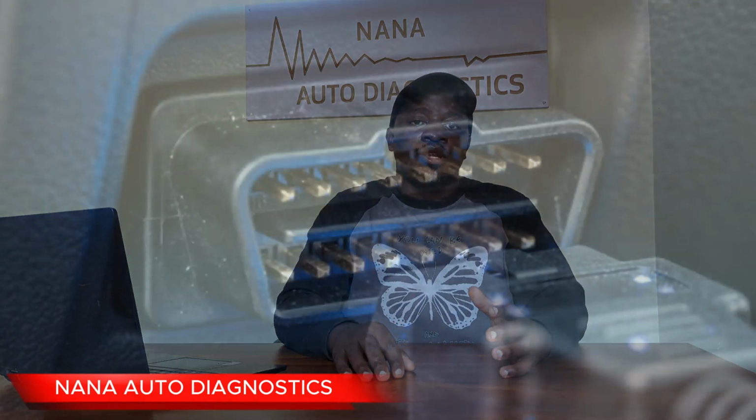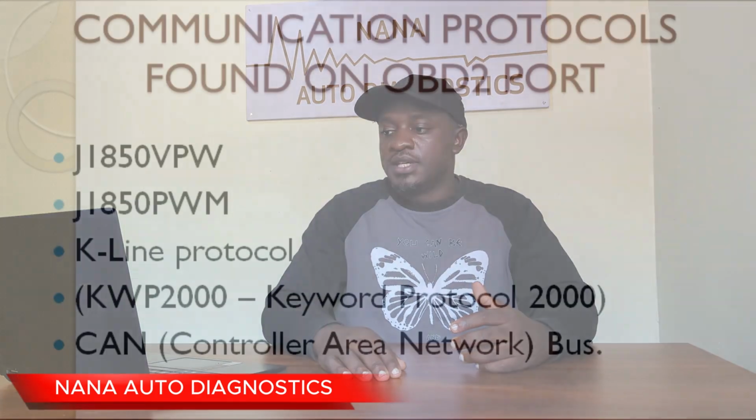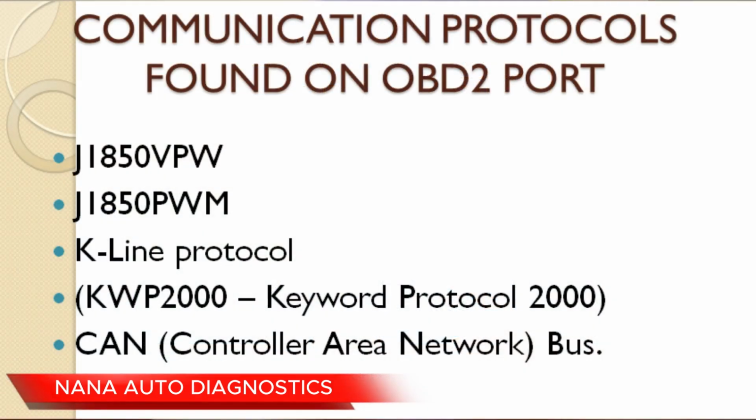It is also important to note that not all these protocols can be accessed on the OBD2 port. Now these are the protocols which can be accessed and tested on the OBD2 port, and they include the J1850 VPW, the J1850 PWM, the K-line protocol, or the upgraded version, which is KWP 2000, standing for Keyword Protocol 2000, and lastly the CAN, which is the Controller Area Network.